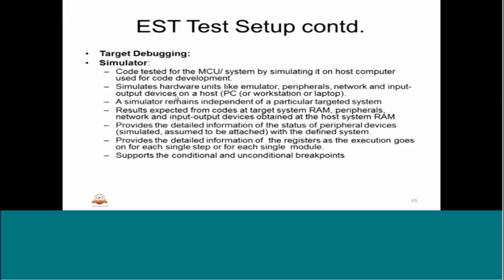For that, what we need to do is first the developed code should be compiled, cross compiled. I think I have explained what cross compilation is in embedded C. Anyway, that is part of the embedded system basics. We use a cross compiler where we have the code developed in the host and compiled for the target.